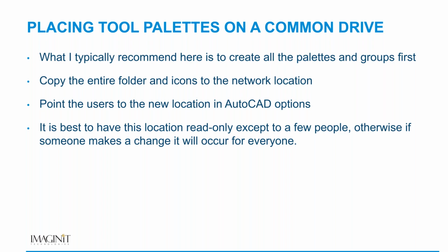Are you able to take custom tool palettes from AutoCAD Architecture and copy them to AutoCAD LT? Yes, you can do that. However, if you are running anything that is architecture specific in AutoCAD, it will not run in AutoCAD LT. I know that AutoCAD Architecture does have some very specific tool catalogs and some other stuff, but if it's basic functionality of AutoCAD Architecture, you should be able to do that.